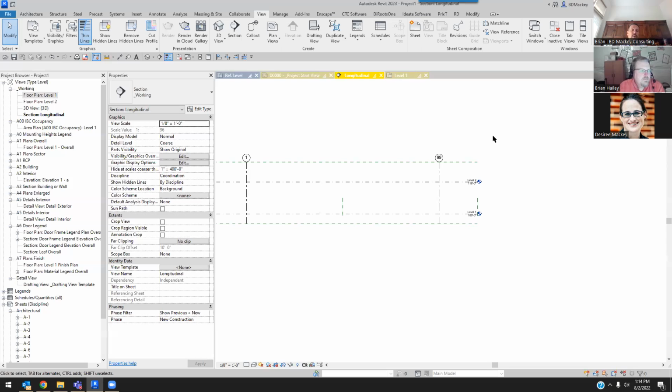So that's what I always recommend, because if you're going to go through and model a beam in, why not have something that also models the studs, your trimmers and your king studs? Why not? Because then we put it there and we can see the stud pack, and that can start to affect things. I've been in locations where we had a very heavy load coming down, and there were 3 king studs and 3 trimmer studs, which is a huge deal for the light switches or anything else trying to get coordinated in there.